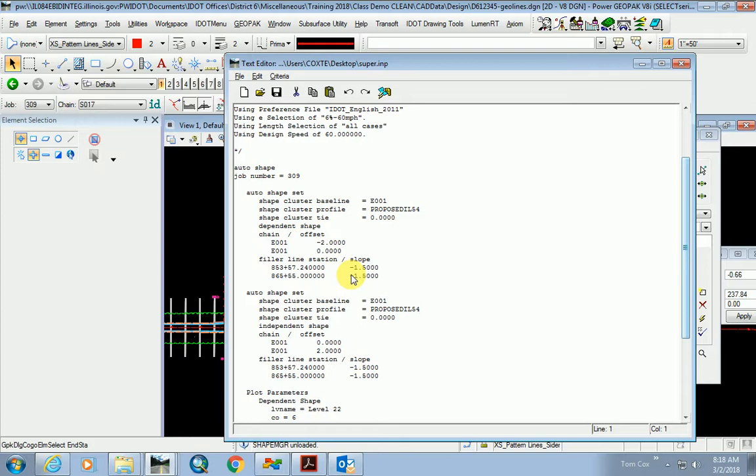You can take a look. There's a real good diagram of it as a CAD standard. So we actually include that in most every job, even resurfacing projects, because the way that super elevation transitions are handled is different than when the roads were originally built. It used to be based on design speed, you'd have a total transition length, and you'd take that total transition, and 2/3 was before the PC, then 1/3 was on the curve.